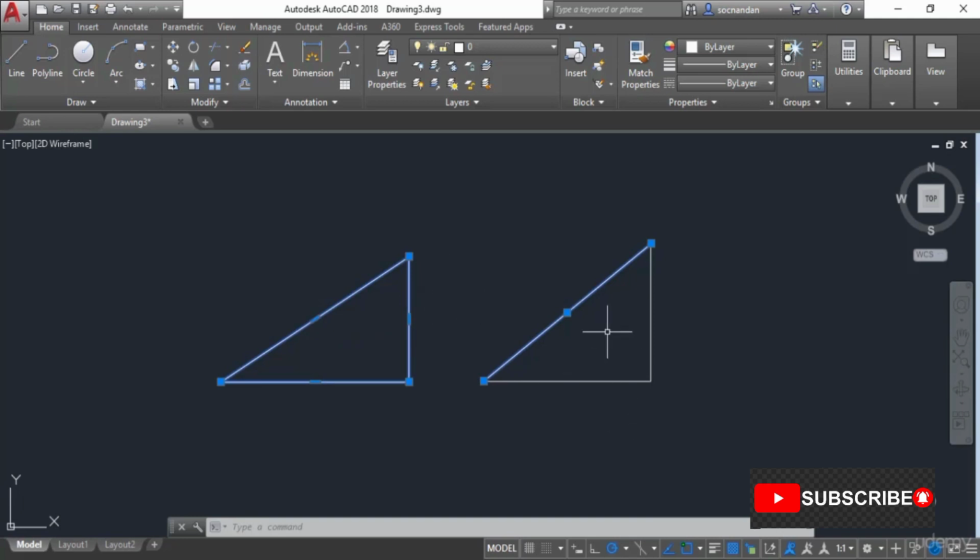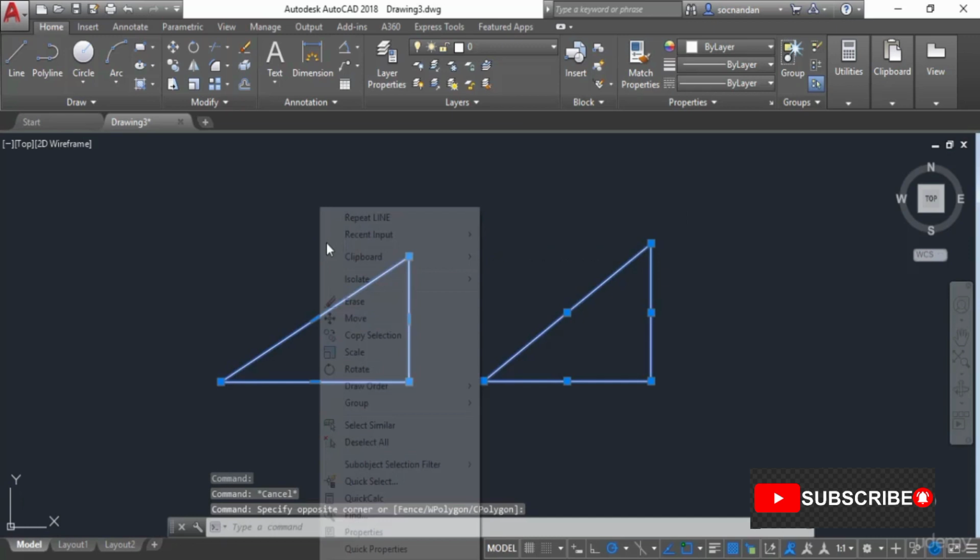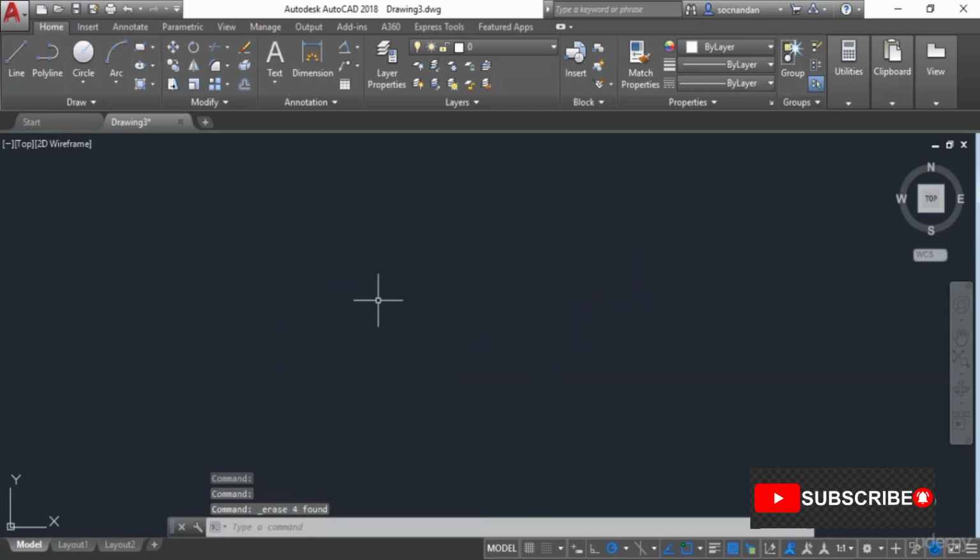So that's one of the basic differences between a polyline and a simple line. In this case, the lines are quite separate from each other, and in case of polyline, they are combined into a single unit. Now let's erase them. Polyline has also many other properties. So let's start this polyline, and now I'll click at a point to start the polyline, and now look at the command line. Here we have some other options related to the polyline.